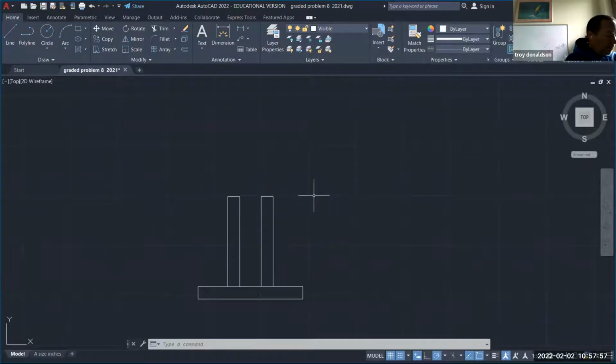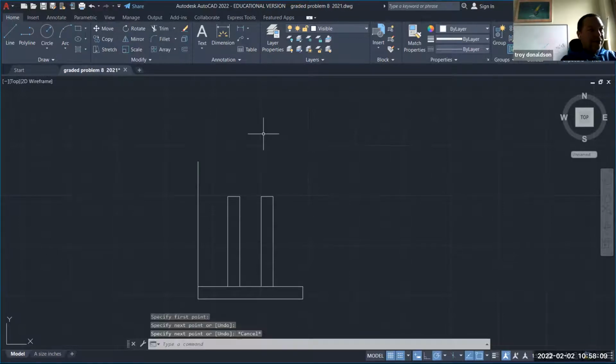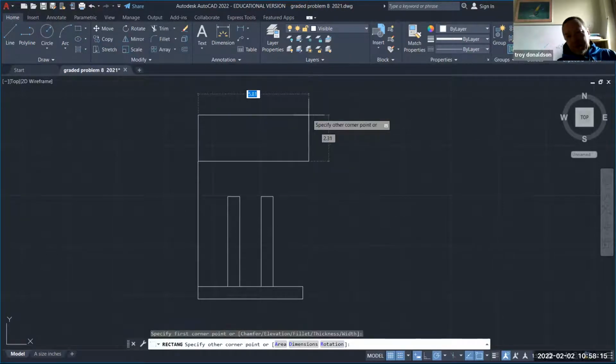I will have a top view that's going to be in a rectangle that is 5.5 by 3. So I might want to get that in there, right? So there's a marker line to keep it in projection. And then I'm going to do a rectangle. And I'm going to put in coordinates. So that's the at symbol.